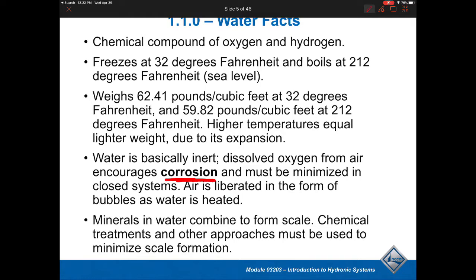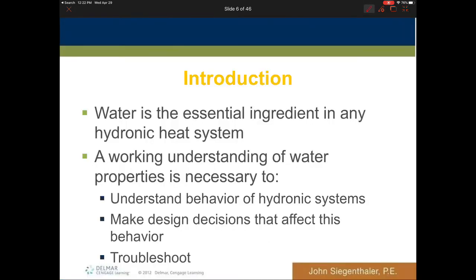Any systems using a heat exchanger, let's say an ice machine using a coaxial coil or any water-cooled system, could have this become a problem. So it is something we worry about. Nowadays, we are very cognizant that water chemistry is something we need to concern ourselves with, due to corrosion inside boilers, heat exchanger failures and things like that, and a lot of that deals with the hazardous parts of the water when we bring it in.